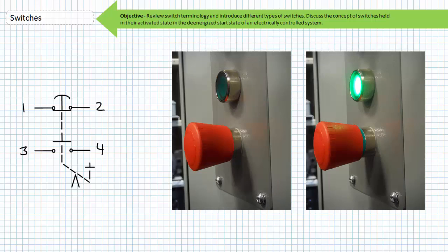Quick note on resetting emergency stop buttons. Resetting an ESTOP isn't as simple as pulling the mushroom button back out. Normally they need to be rotated a half turn for it to be reset. Sometimes the face of the button has an arrow to remind you of this necessity, sometimes it doesn't. Additionally, sometimes emergency stop buttons have a green ring on the stalk of the mushroom to indicate that the switch is in its deactivated, ready, or go state. Look at emergency stops from the side and make sure you see the green band before you return the equipment to service.